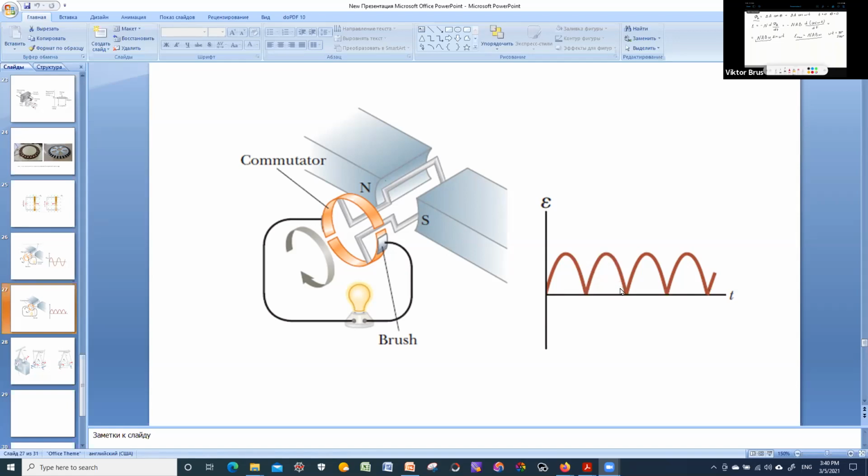And we again get a positive signal generated by such a DC generator. So DC means that we don't change the direction of electromotive force and electric current. In this case, it is always positive. So it is not constant; we get some pulses of voltage and current. However, they are always in the same direction, and that's why we can already call this current DC current.